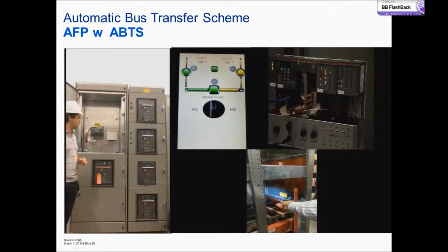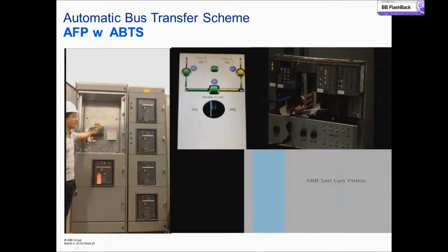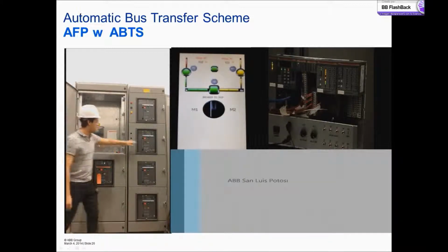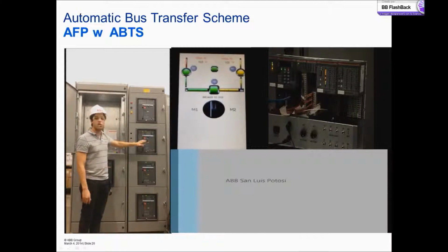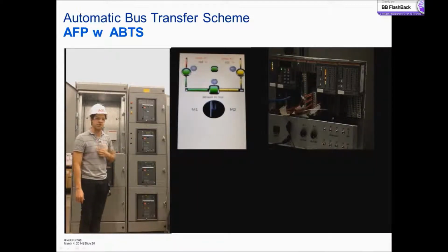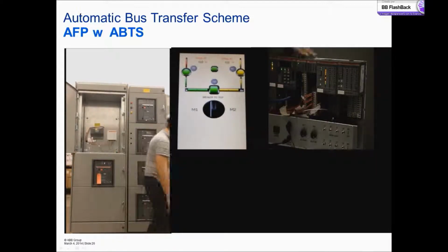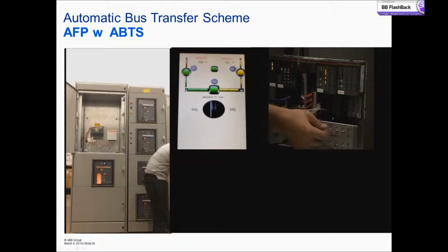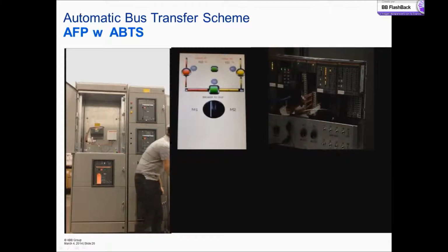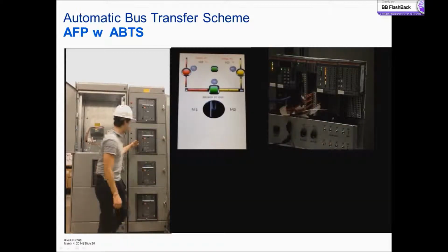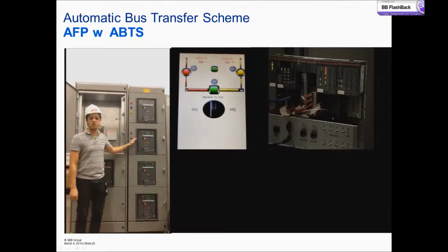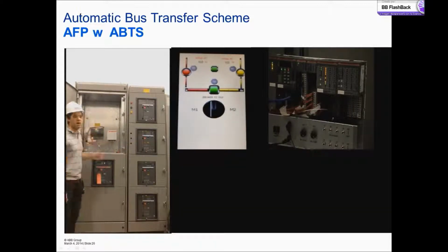So there you go, the flash. We have an alarm and it is open, and this one will not close until we reset. We put the reset in our PLC. So with this Boolean input, we're going to simulate our reset. So now it's closed because I put a reset on the failure of the arc flash.